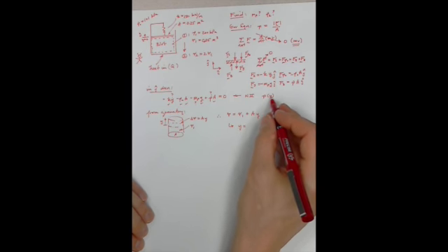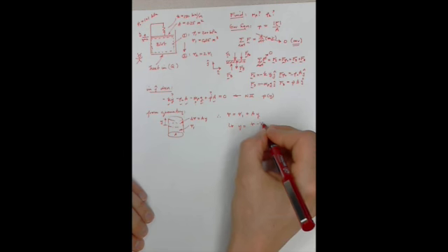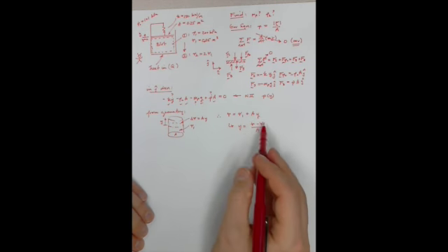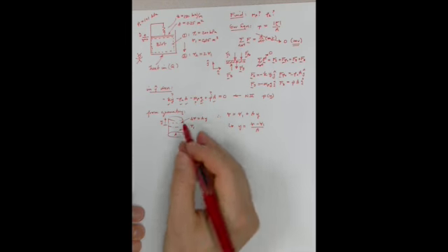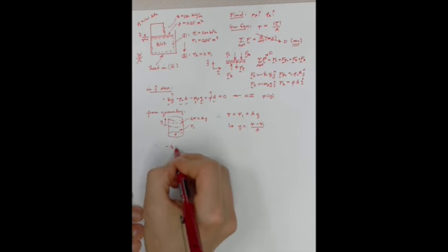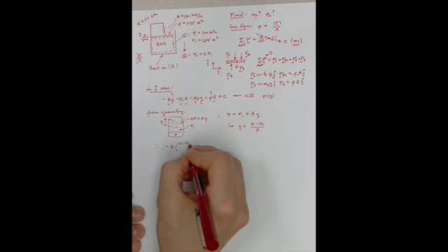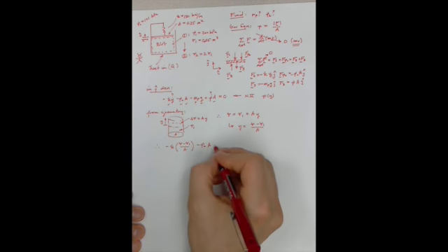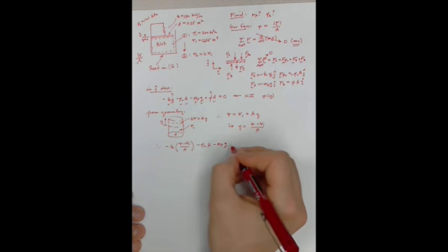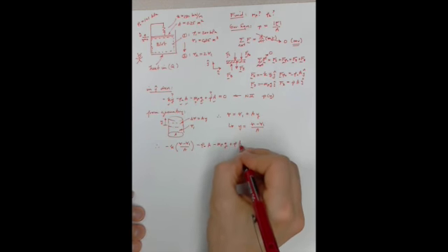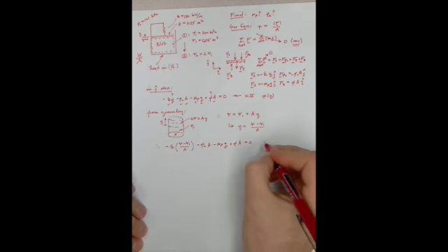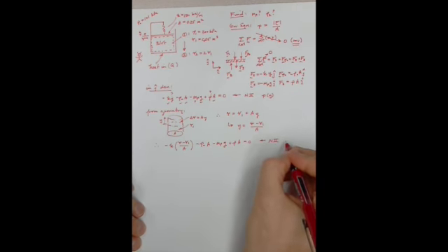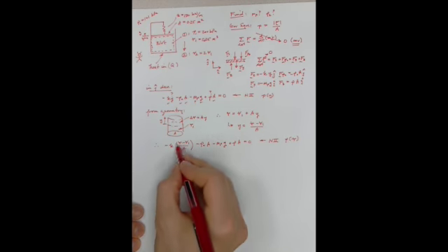So instead of p as a function of y, I'd have p as a function of v. So v minus v1 over a is my height. Plugging this in, I have minus k times v minus v1 over a, minus p naught times a, minus the mass of the piston times gravity, plus p times a equals 0. So this is still Newton's second law. But now what it's given us is the pressure as a function of volume. Now the new independent variable here will be volume.